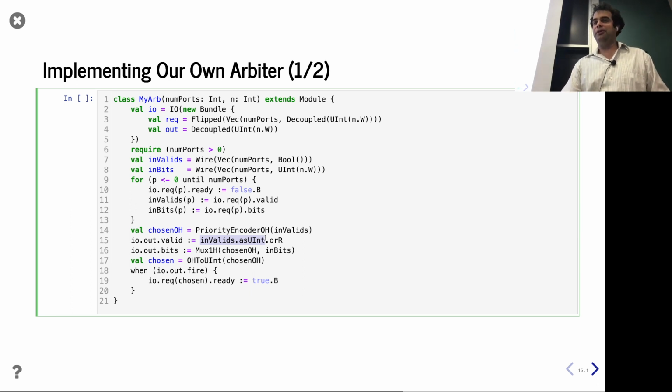So when I first defined one hot earlier in today's lecture, I was saying the one hot rigidly requires it must be exactly one. Chisel takes a more extended view of that, which is if none of the inputs are one, you can have 0 sometimes, right? Which is not normally allowed for one hot encoding. So in that case, if all of these things are 0 coming into this priority encoder, the output's going to be 0, right? So maybe you can revise the definition for this priority encoder one hot: if you give it a non-zero value, it'll give you a one hot encoding. If you give it a 0 value, it'll give you a 0 encoding coming out.